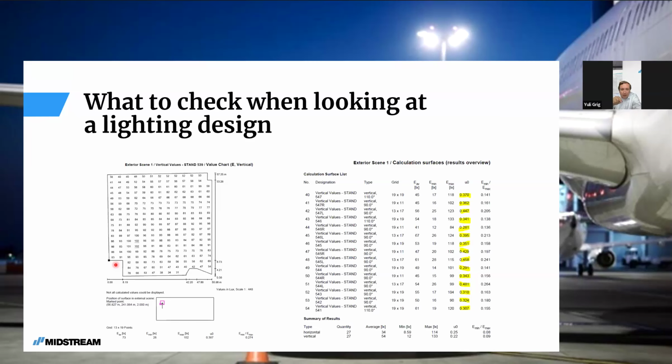Now, in the bottom left, you see Eav. That shows you the average level. So the average of this stand is 73. Very high average. It's taken from a real case example. Then next to it you have E-min, so that's the minimum level. We probably can't identify that on this grid because it's hidden or not shown amongst all the points, but it is in there.